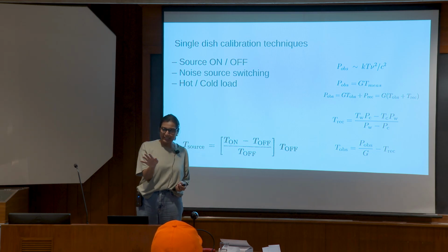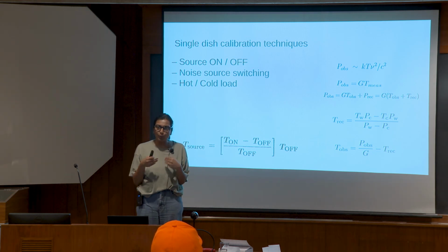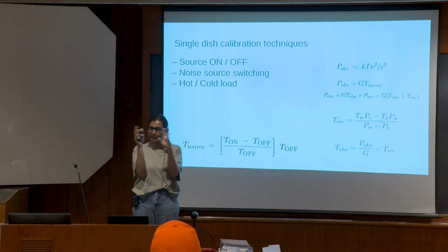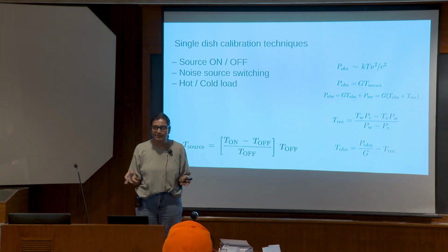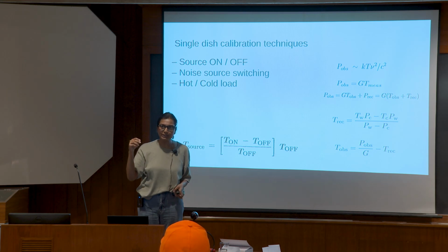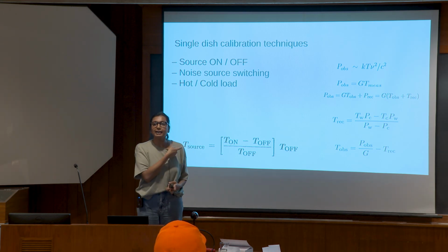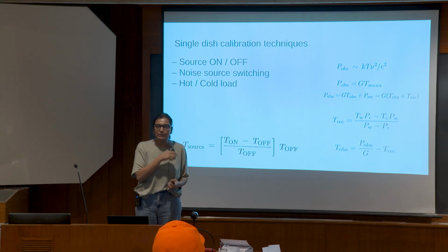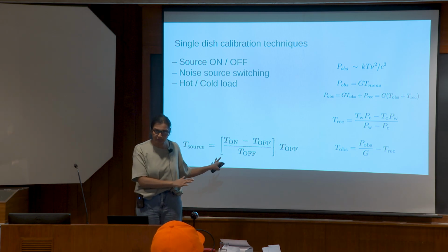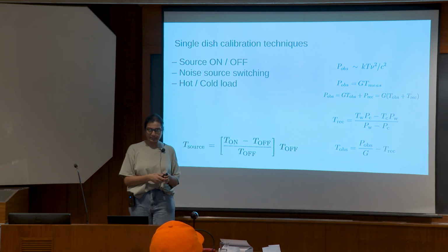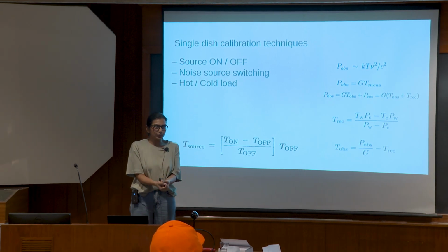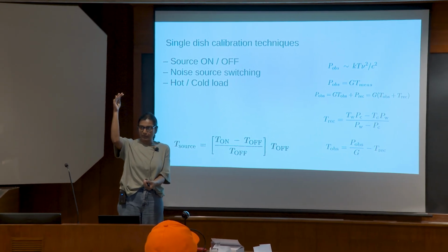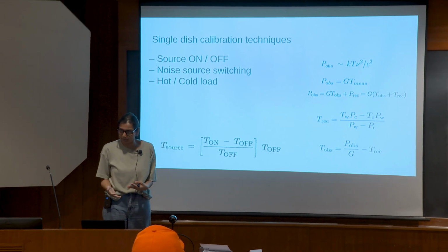Yes, so that's called linearity. So you want to try to keep the object you're sticking in front of your antenna or receiver in the same order of magnitude as the object I'm seeing. Because if I saturate the receiver, the gain is no longer linear. It will change. That means my calibration will fail. So we have to take care of these things. And then finally, you can convert that random number you measured at your receiver, looking at your source, to meaningful units like temperature.